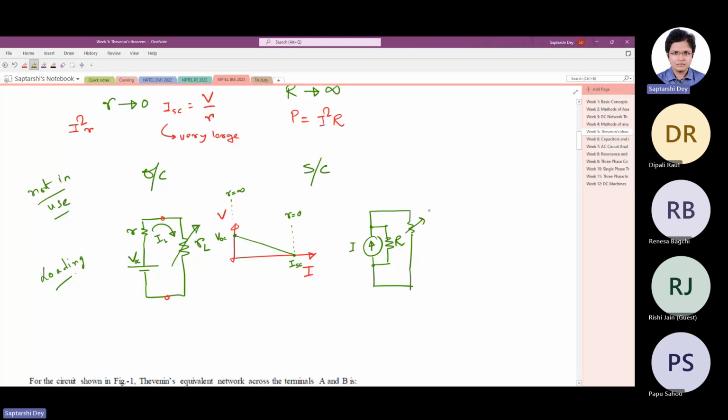Say this is the load resistance RL. Now if you draw, here we have to write V on one axis and I on the other, because what we are getting by changing RL is varying load voltage. And then we are seeing for that much load voltage, how much current is flowing. What you will see is it is again dropping like this.